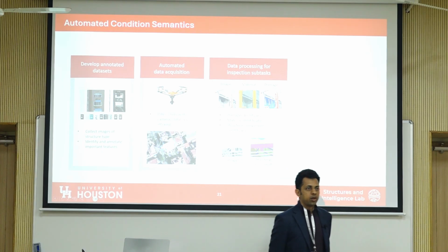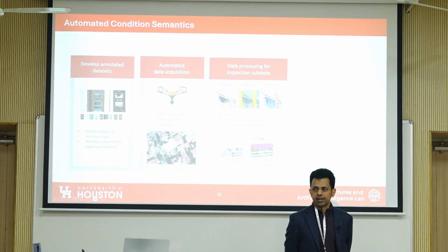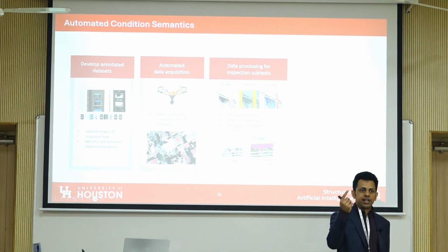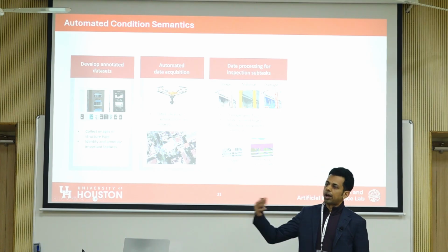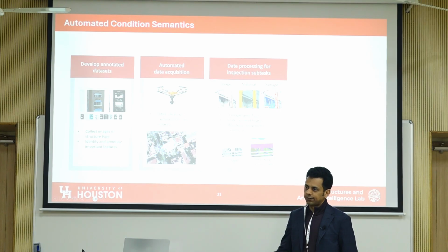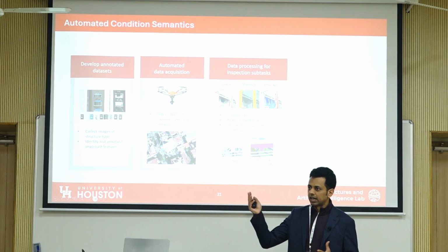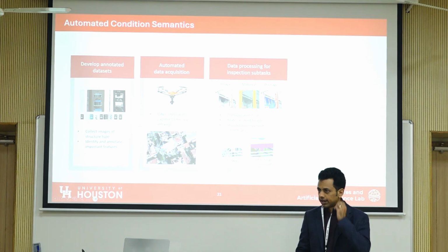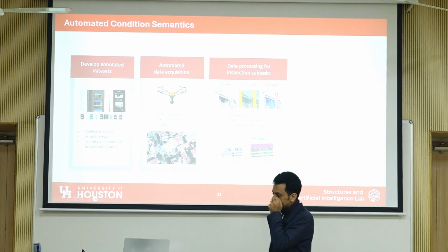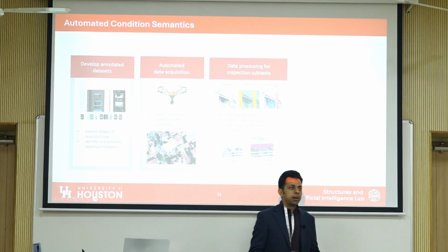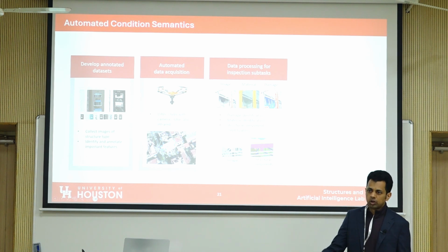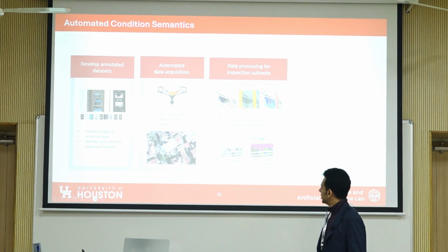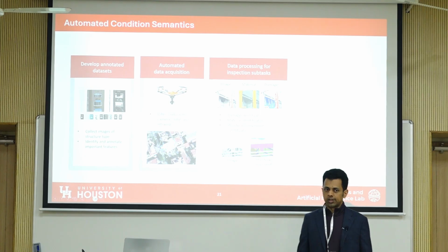Yeah, exactly. You want to know the context in which the damage is occurring. Because if you have a window that's cracked, that is probably not of as much concern as if you have a load-bearing column that's cracked. Right? So the context in which the damage occurs is very important for you to be able to make an assessment about the integrity of the structure, as well as what course of action needs to be taken subsequently. And so that's why we need to extract as much information as possible.